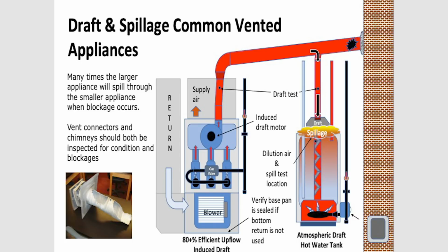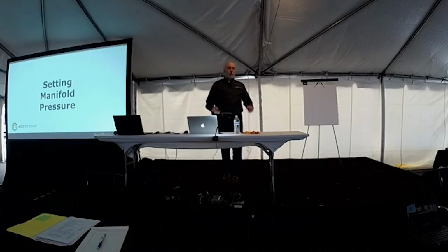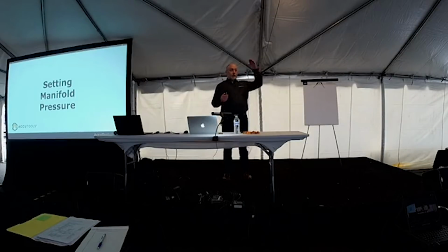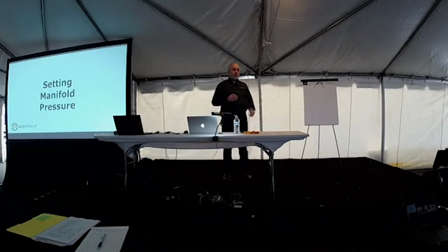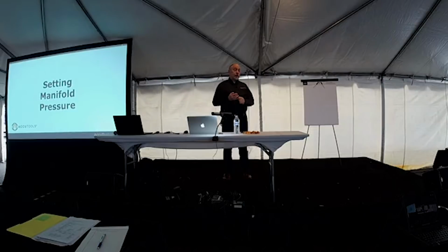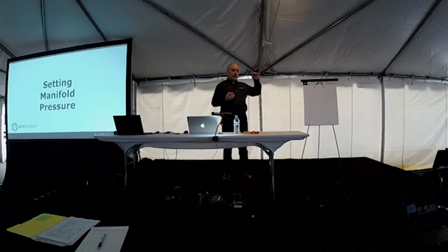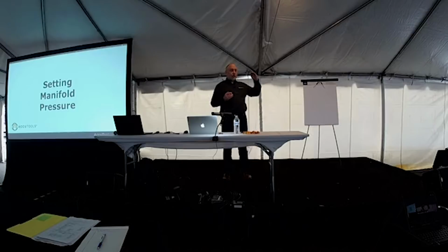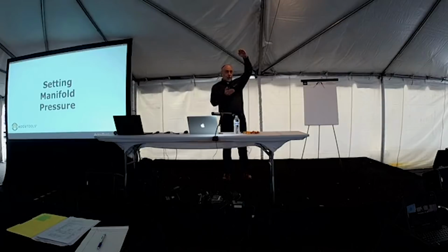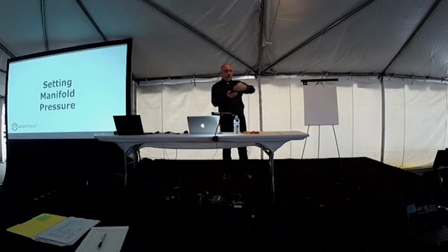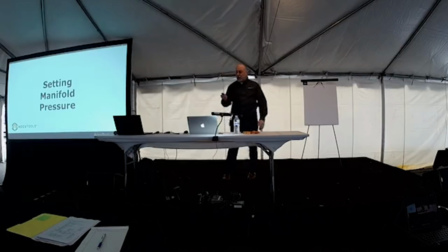But this one here is one that's near and dear to my heart because I've seen this happen more times than one. Well, you can have the Y on there, that helps divert the flue gases in the right direction, but if it builds up and backs up, that's the problem. It doesn't matter, a Y is the correct way of doing it. So normally we'd have like a 3, 4, 5 or a 4, 5, 6, and you'd Y it in. But the problem is when it goes up, if the pressure builds up, it's static pressure, right? It just builds up a pressure in there, and it's got to have somewhere to exhaust itself, so it exhausts out the hot water tank. And that's the most common problem when you see those things melted out there.